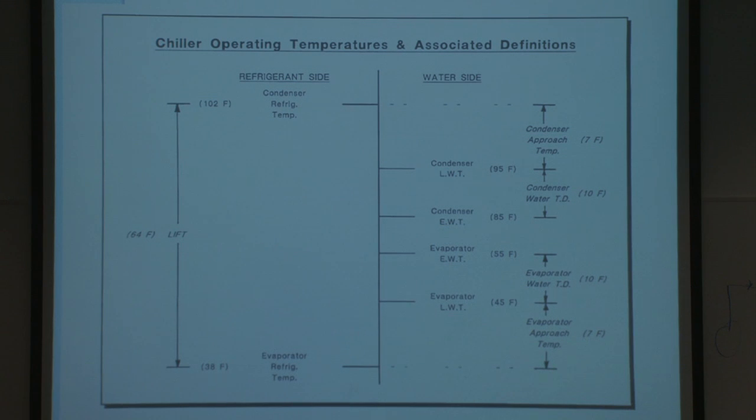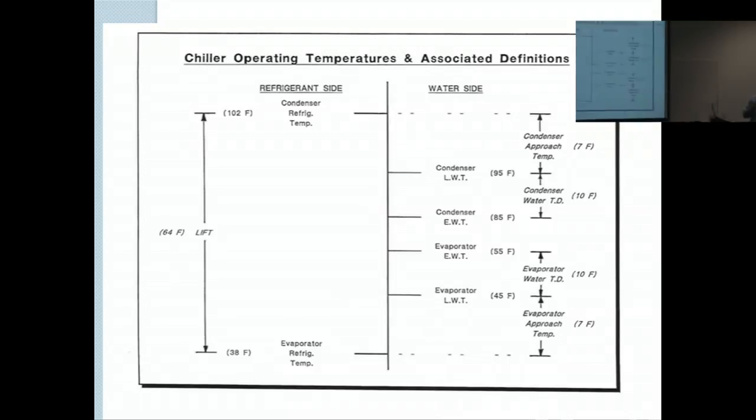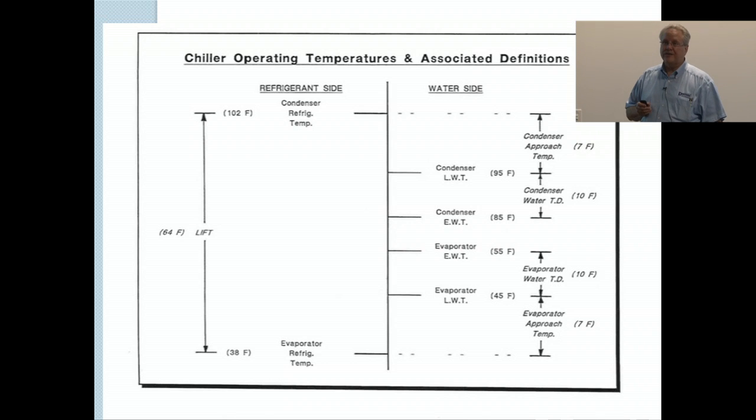I just ran some very rough, quick numbers on a 400-ton chiller, and on a typical office building in this part of the country, it will more than likely cost about $48,000 to $100,000 a year in electric bill to run. So 1.5% is going to be $720 to $1,500 for the year if you just said, well, I'll just wait. It's worth looking at in a timely manner and not waiting.